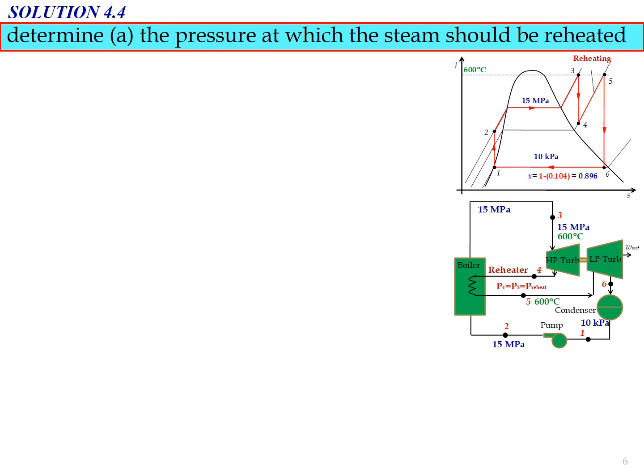So now it is better to determine the important parameters such as entropy and also enthalpy value for each state from state number 1 to state number 6, where we need to make sure that for each state we have at least 2 data. So before we answer the question, we need to determine the enthalpy value for all the states involved.